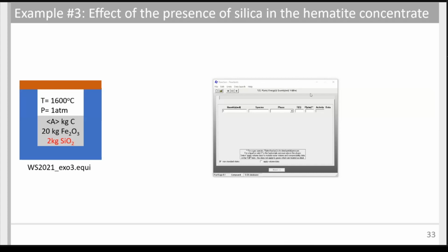So this is the reaction module. You can add reactants, so I'm going to have 2 reactants here, silica as well as 2 mole of carbon. This will generate CO because we're working at high temperature, and liquid silicon. So we'll have 2 mole of CO and 1 mole of silicon. So the first step will be to work under standard condition. You see here that the only variable that I have is the temperature.